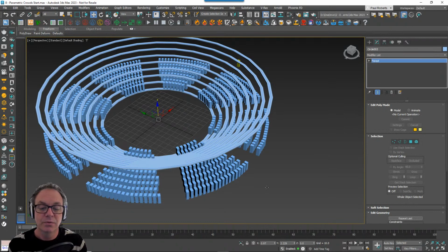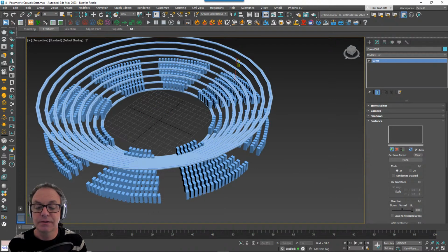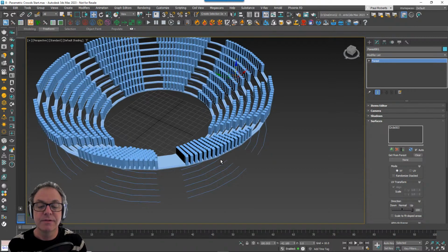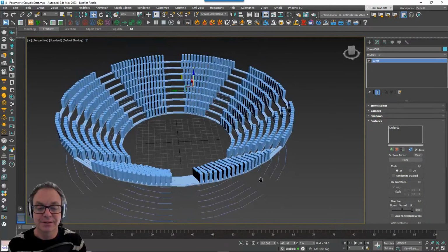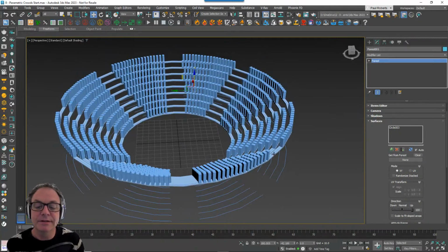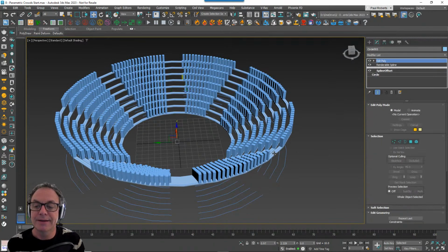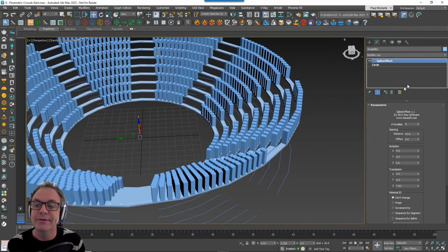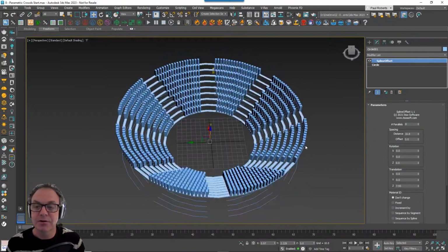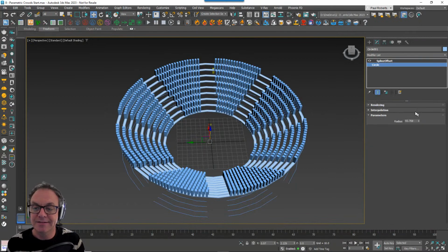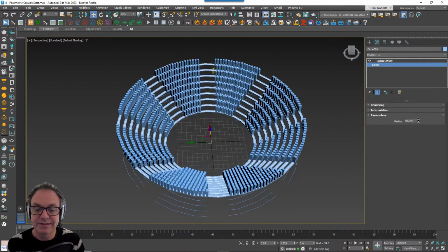And then we can come back into Forest Pack and add that to the surfaces rollout. Oh, it's trying to add itself. There we go. So now they're sat on that. Okay, so that's working great. And the nice thing about that is that it's all fully procedural. So I can come back into this original spline, go back to the circle, and change the radius if I want.